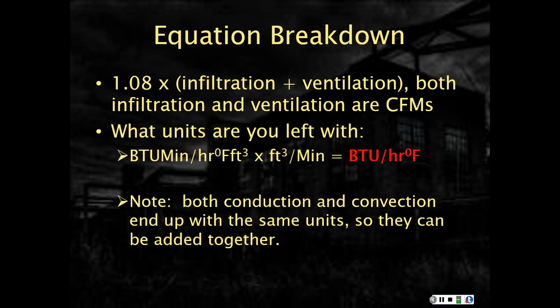The next part of the equation has 1.08, this happens to be the convective portion, times both infiltration and ventilation. In other words, two of our key sources of convective heat transfer. Both infiltration and ventilation need to be in CFM.